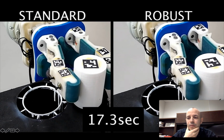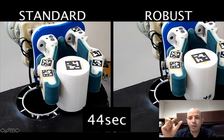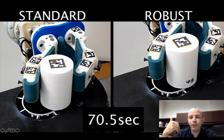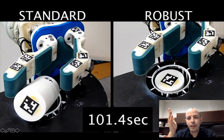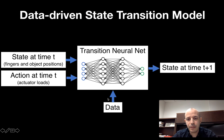And we use this idea of belief space planning using the model that we learned on the robot to perform interesting tasks such as inserting an object inside the hole. And this is done open loop, so there is no sensing being done. We just plan offline, and then we run the plan directly on the physical robot. So it's very sensitive to modeling errors. On the right hand is what we get when we use the probabilistic robust planner, and on the left hand is what we get with the standard deterministic planner. They are both using a model that was learned from data, the Gaussian process model. And this was published at ISRR last year.